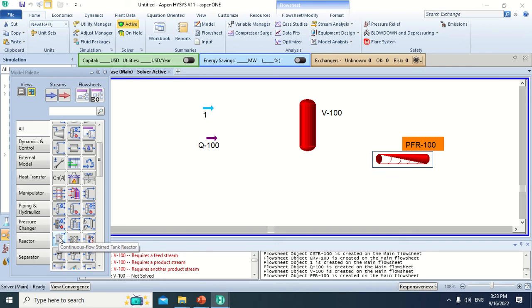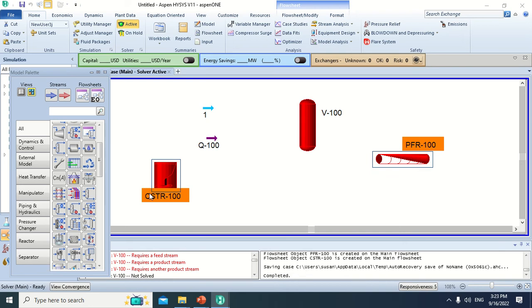This is the tank reactor, or CSTR, and it is really famous. The continuous stirred tank reactor assumes perfect mixing throughout the volume of the reactor, and the outlet conditions are approximated as equal to the conditions inside the reactor. The general reactors, equilibrium reactor, conversion reactor, and Gibbs reactor, each is a CSTR with a specialization in its corresponding Hysys reaction type. The kinetics, equilibrium, and heterogeneous catalysis reaction types can be used with the generic CSTR.